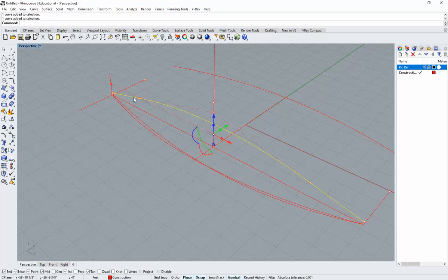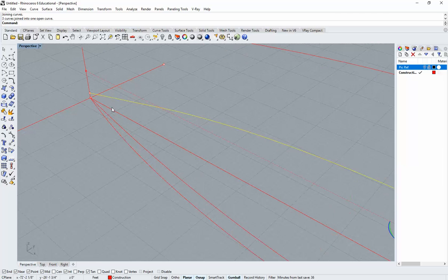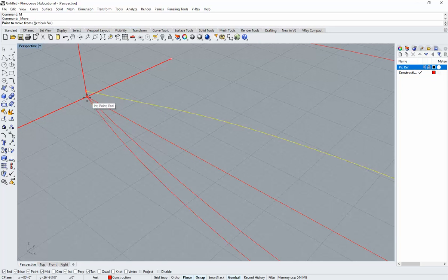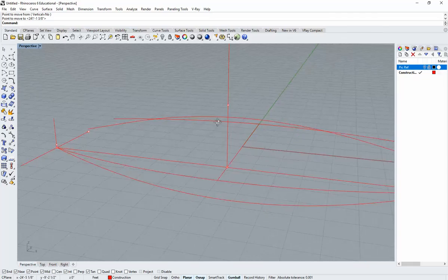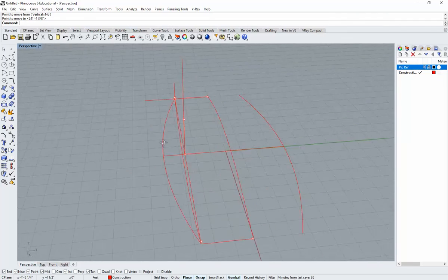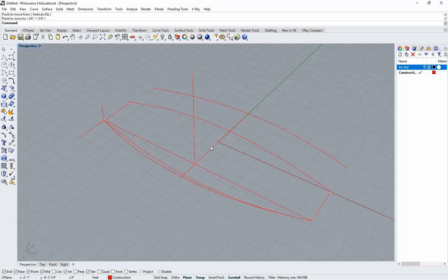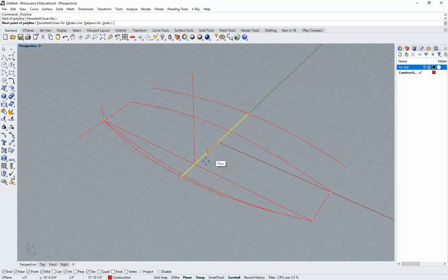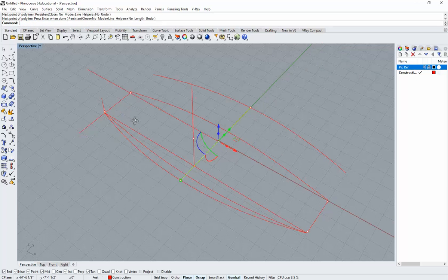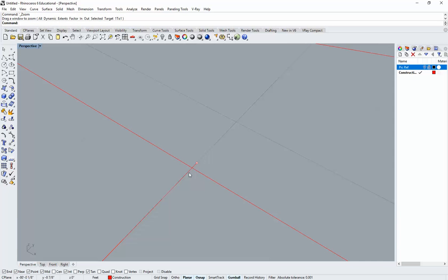And the first thing I'm going to do is join those three segments like this. And then I'm going to move it, typing in move. From that point, I'm going to put it right in the center. We should probably check to see if this is still at the center. So I'm going to move it first, and then I'm going to see if that's actually still centered. Just to make 100% sure. So this is for sure center. This is my midpoint. Draw that across to make sure it intersects. Yeah, see, it looks like we're a little bit off because we made that adjustment earlier.